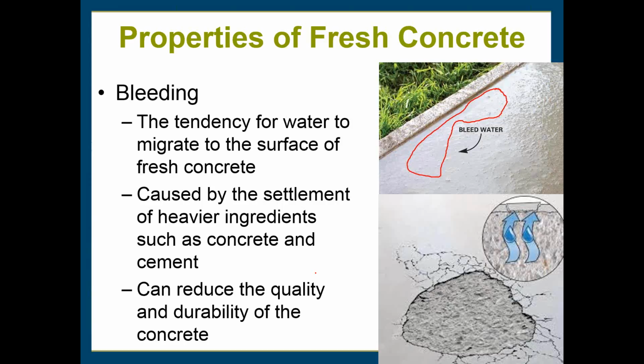And one other note about this, bleed water, it's not a bad thing. It happens, it's common, it just needs to be controlled and not worked back into the concrete while you're finishing the surface.